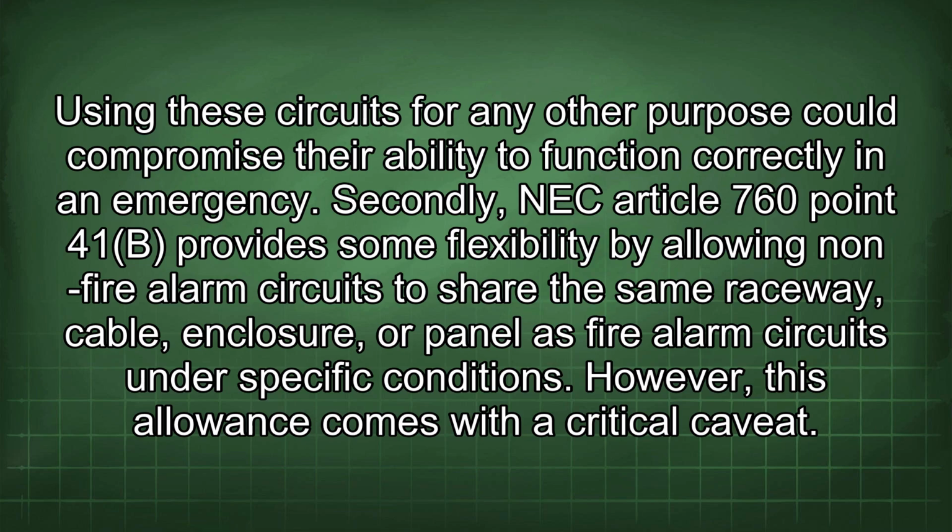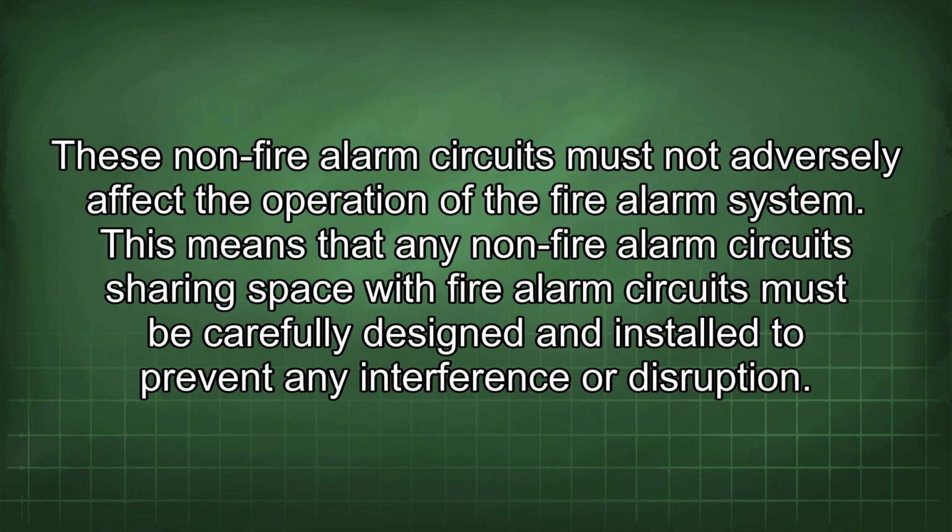Secondly, NEC Article 760.41(b) provides some flexibility by allowing non-fire alarm circuits to share the same raceway, cable, enclosure, or panel as fire alarm circuits under specific conditions. However, this allowance comes with a critical caveat. These non-fire alarm circuits must not adversely affect the operation of the fire alarm system. This means that any non-fire alarm circuit sharing space with fire alarm circuits must be carefully designed and installed to prevent any interference or disruption.